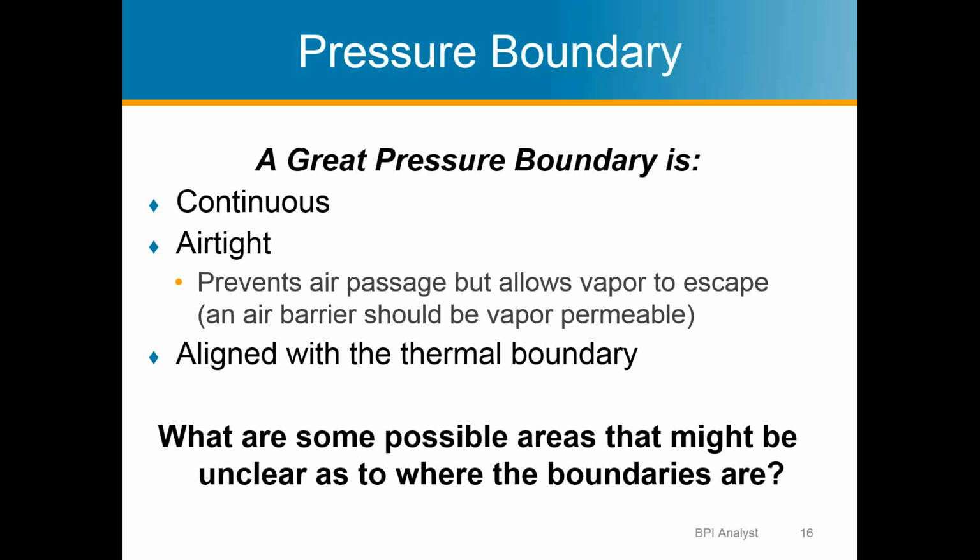It takes a special contractor to actually six-side, which is what we call that. So it's where you put the pressure boundary on the wall and not make the bathtub the pressure boundary. Other areas would be typically chimneys. Modern day chimneys are just a wood framed appendage to the house, and so there might be insulation inside this wood framed chimney, but there wouldn't be an air barrier on the inside of the chimney. It would be like the drywall where the chimney's surface of the wall inside.